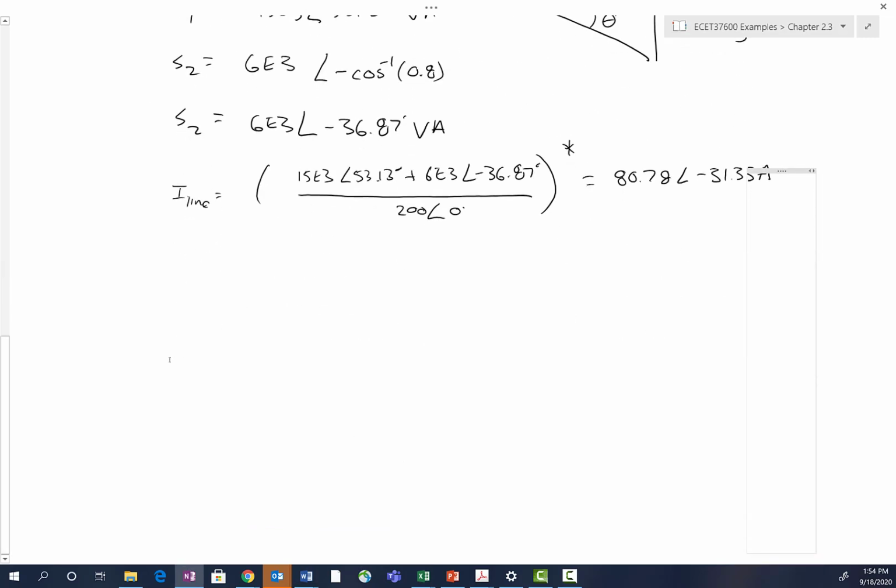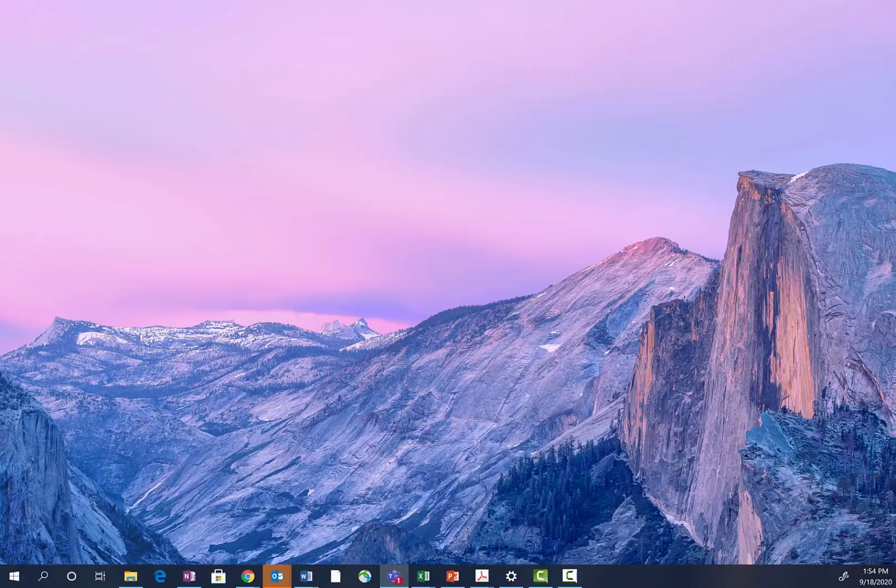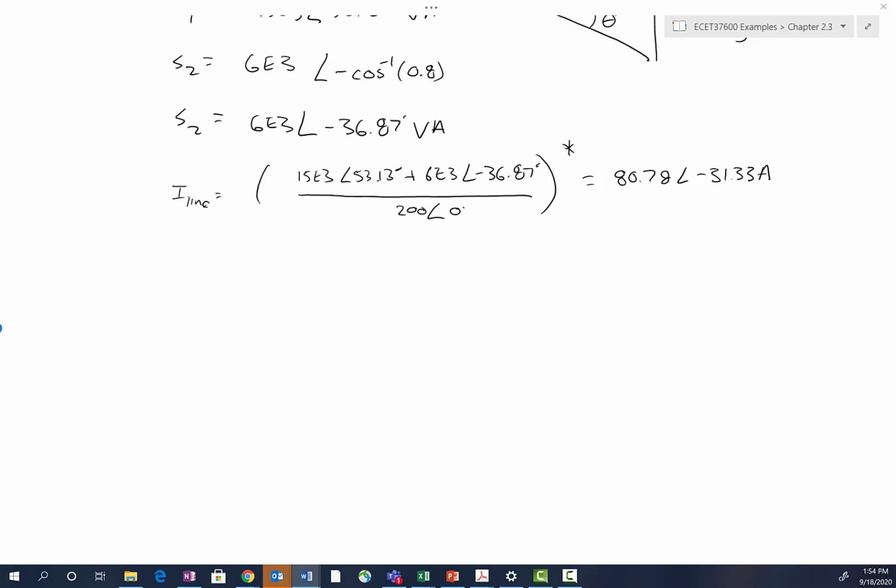Right. So from the formulation that I set up for you earlier, what we now need to do is calculate the source voltage from the load voltage plus the line current times the distribution line impedance, which was J1 ohm.